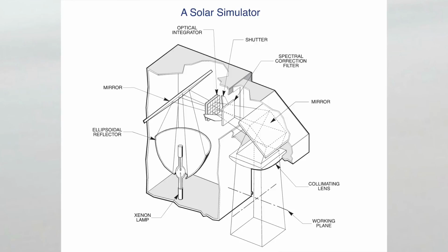And this is important because most light sources, like the source that we have here, if you look at it close enough, this is pretty compact, it's about that big. In other words, if you look at a bulb up close, it looks very non-uniform. You see the shape of the filament and so on. And that's bad, right? Because the solar cell, you want it to be uniformly illuminated. If you have hot spots, that's pretty bad usually. You have some weird physics going on. In fact, you have variations in carrier density, which is not good at all. You end up with much lower efficiency than otherwise. So that's what this does.